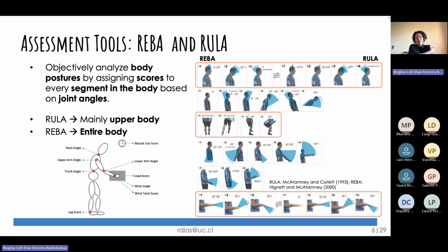And toward my presentation, I'm going to mention two different tools that I use to measure these ergonomic risks. So I use REBA and RULA, which are definitely not developed by me. They are tools that are out there and the industry already uses them to measure these ergonomic risks. So they are really good in our case, in industrialized construction, because they consider the posture of the worker, according to the angles that we have in different body segments, we have different scores.